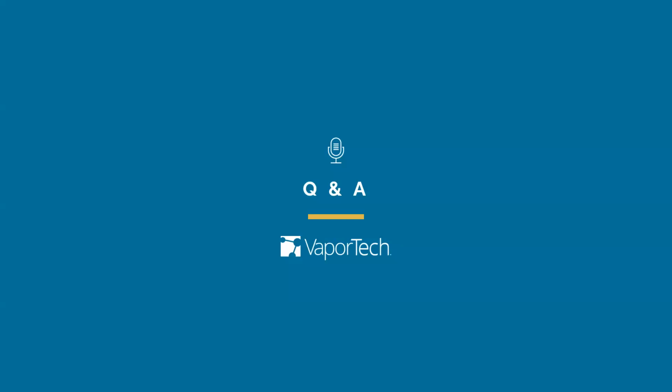With PVD, if you do sputtering, you do have to go to a very high temperature to get the coating that you want. And then you have to watch what is the maximum temperature that your tool can still take. With thermal CVD, you have to be even more careful. Thermal CVD normally is used more for carbide tools, for instance, not as much for tool steel. PECVD you can apply to both. Again, we're talking about diamond-like carbon in this case. What's the thickness that can be achieved? I think we talked about that.